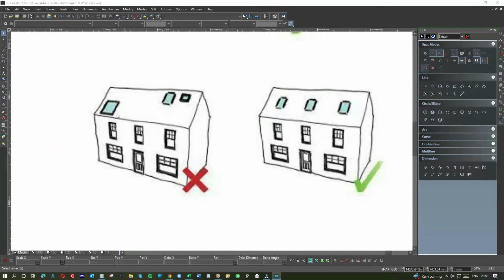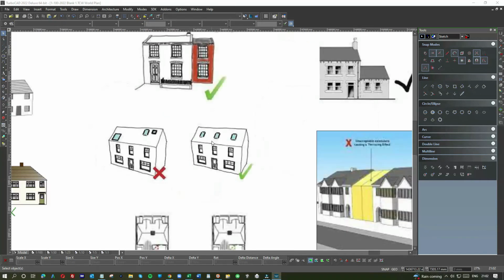This one's a bit simpler. Front facade is fine, front elevation is fine, double fronted house. 3 Velux windows in the roof here. Here we're all over the place, so I'm not saying that you wouldn't get planning permission for that, but it's not good design, and maybe there's something going on inside that necessitates something like that, but it's unlikely you'd get planning for something as ugly as that. So I generally try to aim for the windows decently spaced out, and as you can see, these line up with the first floor, which is always good. So if you're doing Velux windows, before you just pop them in anywhere, see how it works with the elevations, etc.